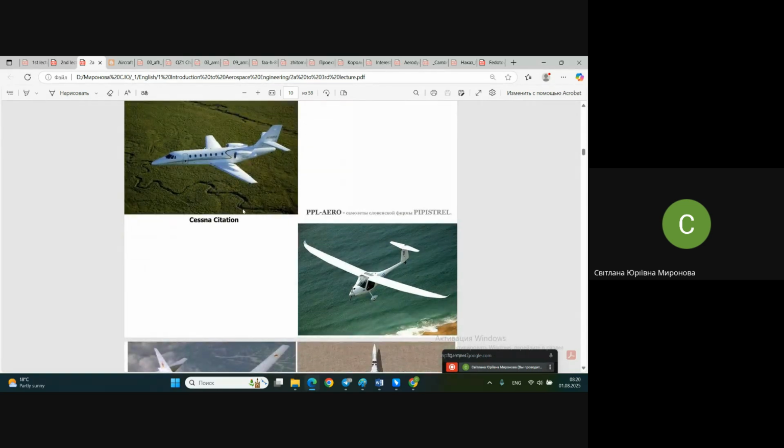And this wing area, proportionally with respect to the fuselage size and other sizes of the airplane, is much less. And this wing, with respect to the sizes of the airplane, is much greater. So the relative area of the wing here is more. And it means that this airplane flies with low speeds. As already said, this aspect ratio also screams to us that it's a slow airplane.